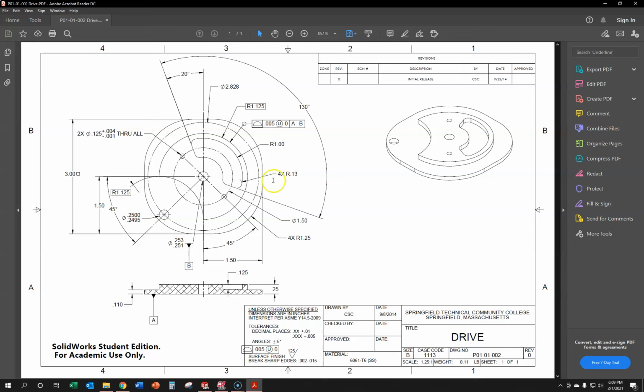Normally what you would do is probably do that in the tool room first, especially if you're making one of these. Maybe you have someone already square the block up for you without doing the extra setups just to get these edges square. What I'd like to do just to make it simpler for us is I'm going to go ahead and say that we're going to use a stock block that is 3¼ by 3¼ and what we'll do is we'll go extra on the thickness. So we'll use the extra thickness for work holding,